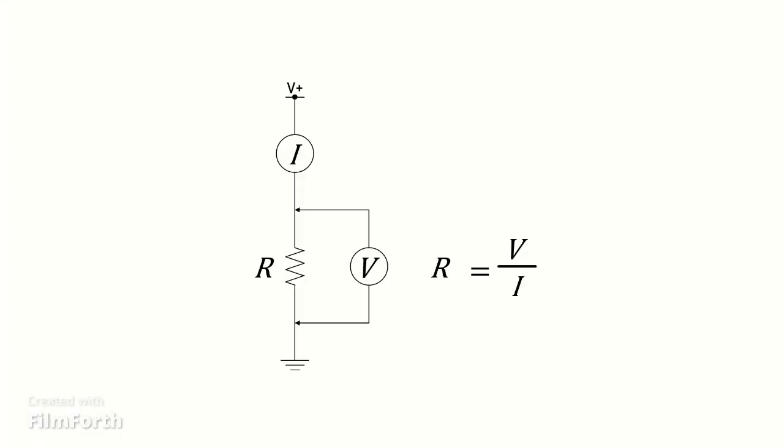There is no instrument that can measure resistance directly. Instruments measure resistance by applying an electric current through the component or device and then measuring the voltage drop across it. Then, using Ohm's law, the instrument calculates the resistance by dividing the voltage by the current. Other circuits inside the instrument will then convert this resistance to the equivalent temperature. And that's how resistance is measured. I think it's important for you to know this before we go into the details of how RTD instruments work.